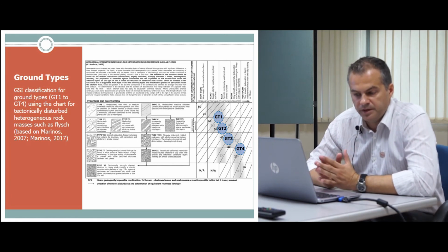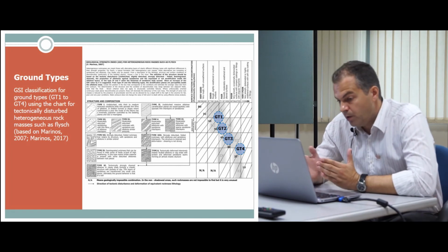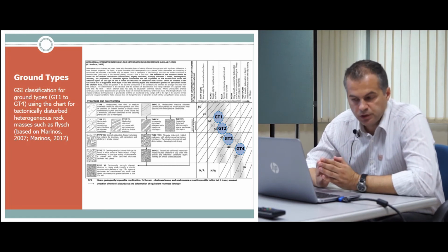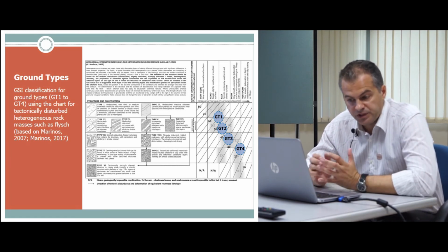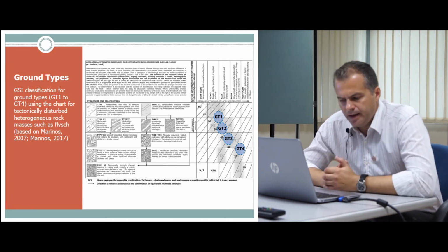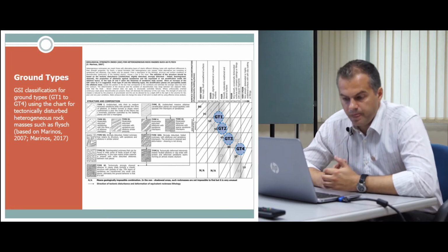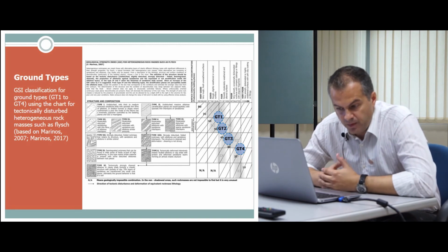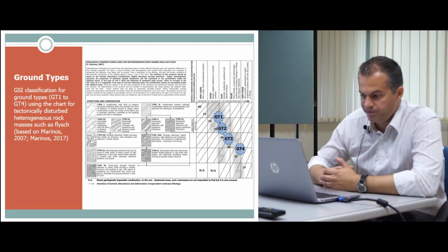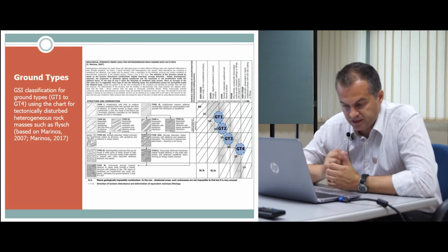The key parameters are the lithology, the UCS of the intact rock, the GSI or any other system used, the distance of discontinuities, friction of these discontinuities, JRC, the persistence of the discontinuities, anything that will dictate the behavior of the rock mass. And then we can determine the parameters from the Mohr-Coulomb failure envelope using the Hoek-Brown and the rock data sets from RocScience.